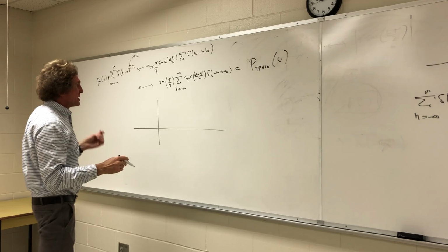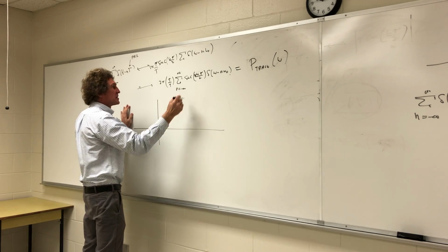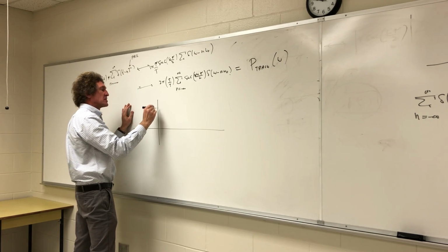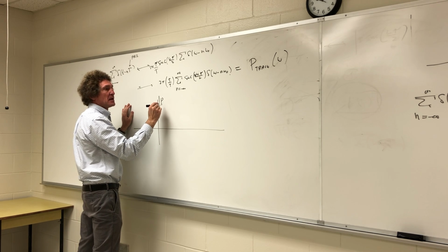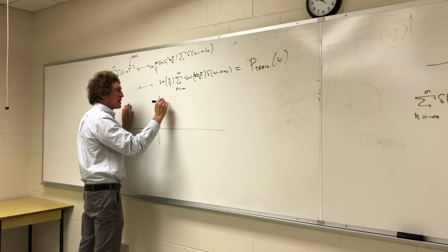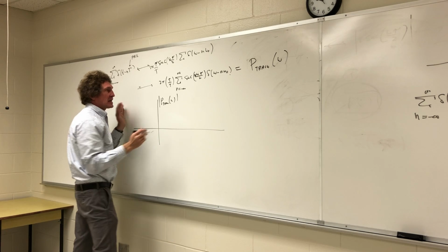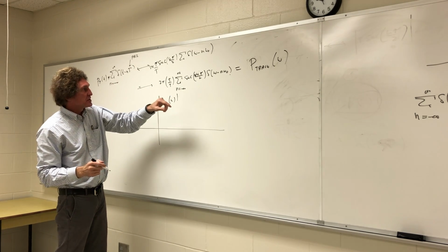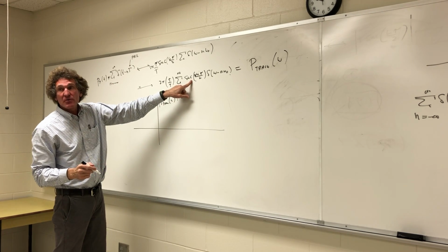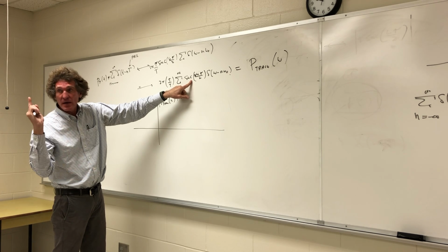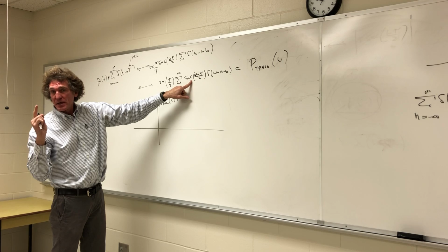Well, what does it look like? Here's the way you do this. First, let's do the magnitude of it. If I want the magnitude of P train of omega, at 0, when the delta function is 0, the sinc function is 0 as well, right? That would be n equals 0. The sinc of 0 is 1, correct, class? Y'all remember that? Sinc of 0 is 1.